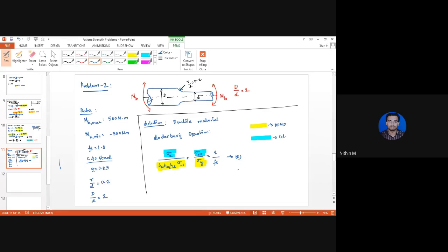So we can substitute the expressions for sigma M, sigma A, and the values of endurance limit in its modified form and sigma Y to obtain the value of the diameter. So this is how we solve the problem. The first thing that we shall do is open table 1.6 and obtain the values for sigma Y and sigma minus 1 for the component.